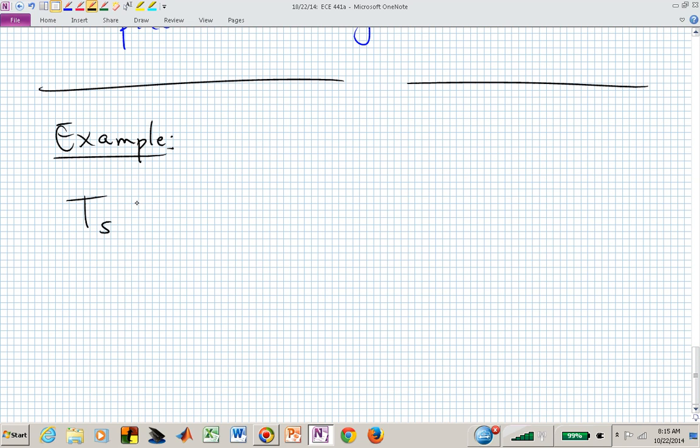Suppose somebody says, and maybe for it to be significant, maybe it's your boss. Your boss now says, I want a settling time less than 1 second. If she's now said, I want a settling time less than 1 second, what picture do you see? Do you see a mental image? And what plane are you in or on? You're in the complex S-plane in a particular location. You're probably stable, so you're in the left half S-plane.